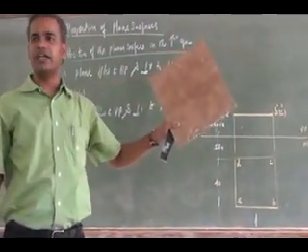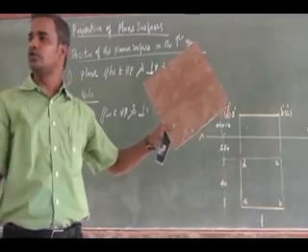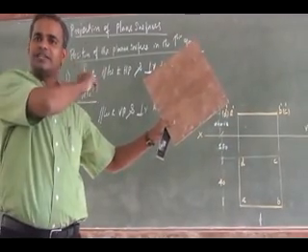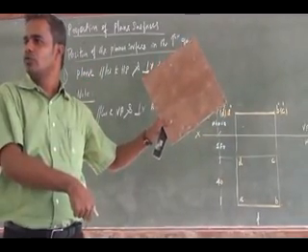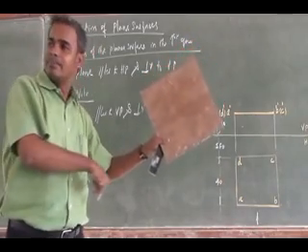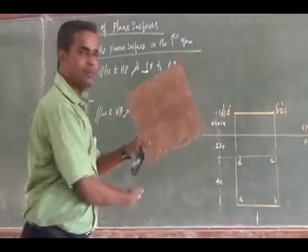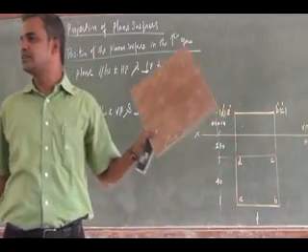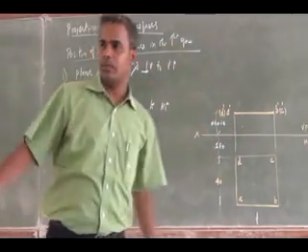So now in this orientation, where will I obtain the true shape? In the vertical plane. That is, in the front view I will obtain the true shape. The top view will be a straight line, parallel to the reference line. Right? Is it clear?